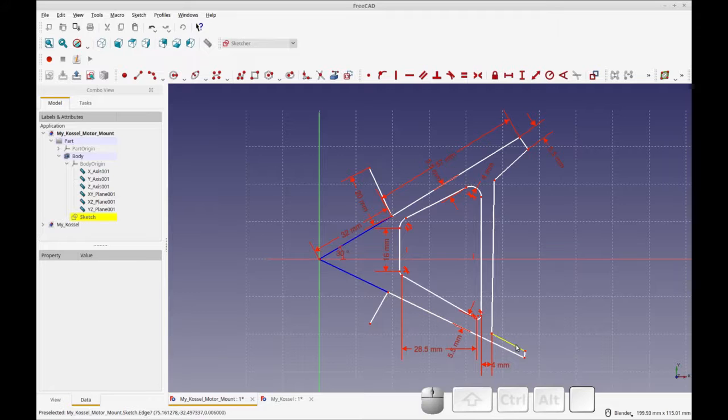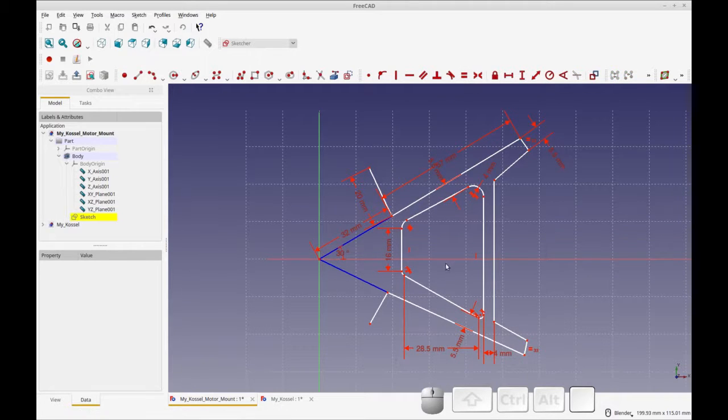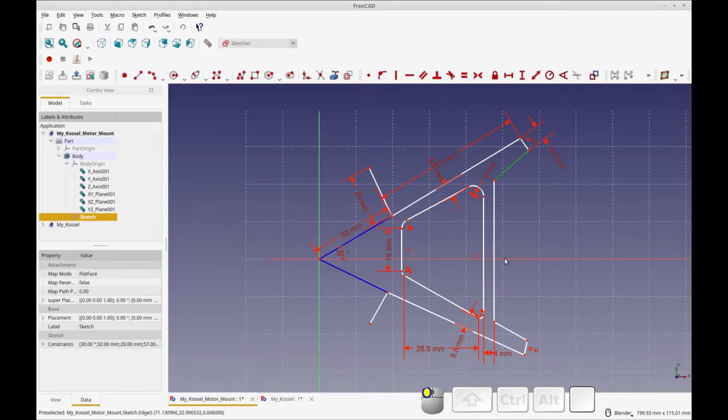The constraint solver can really just throw stuff out of whack. It's got a lot to think about. I'm not faulting it. Okay, so those are all the distance constraints, and we're going to move on from there. So now we're going to set the equality constraints. There's only a couple of equality constraints, and you'll see how it'll even start to shape up even more. So these will be equal, and then this centerpiece will be equal.